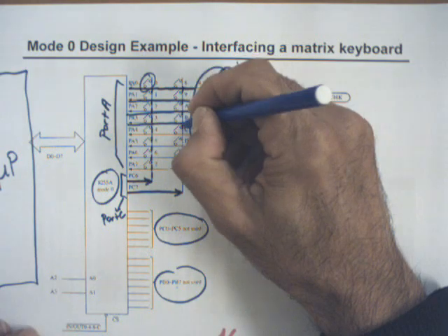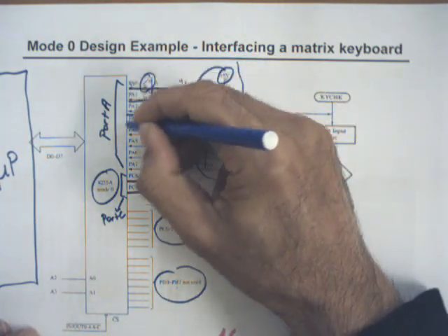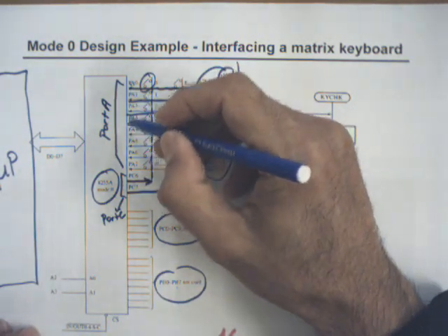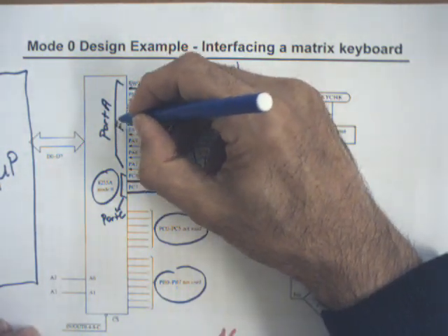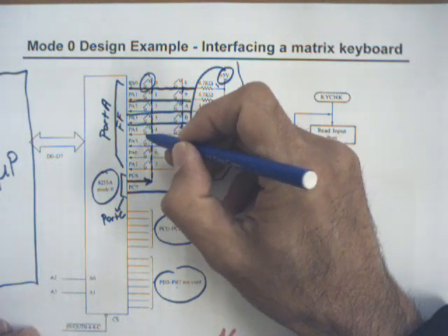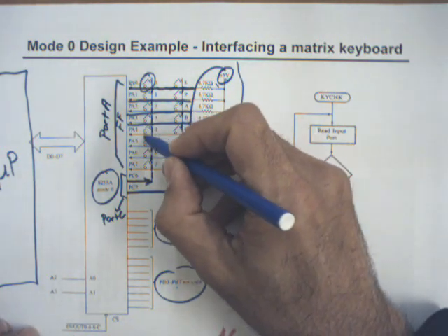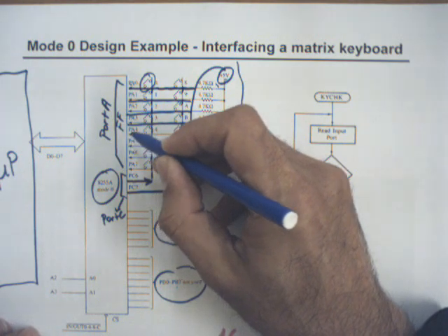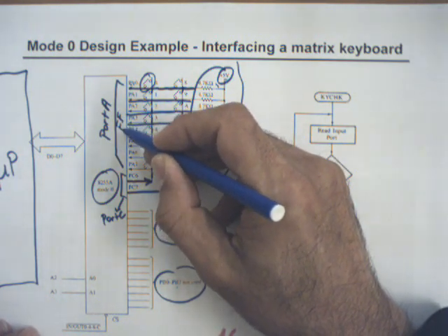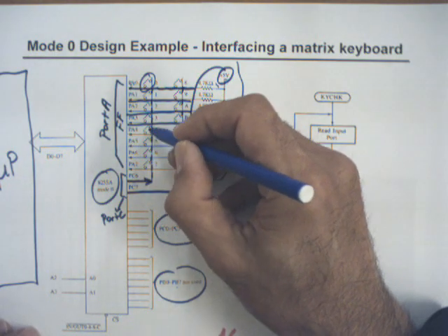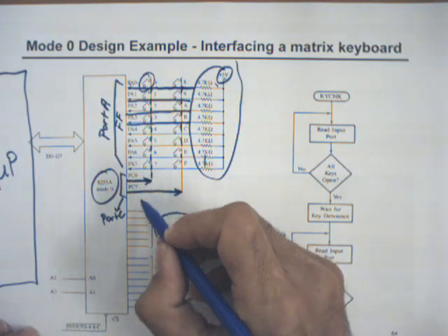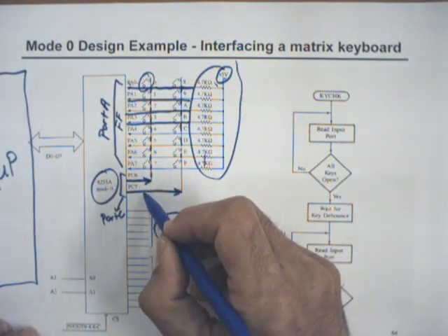When no keys are pressed, all receive high information. So the hexadecimal information is FF. If any key is pressed here, then the associated bit at that pin would be low, so you receive another information, so you can detect which key is pressed when you send low and high from here.